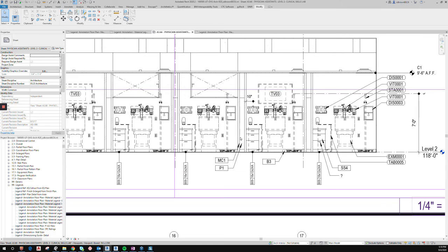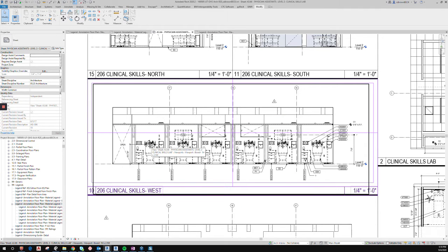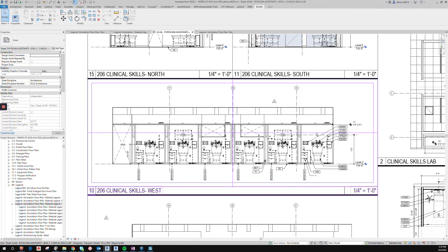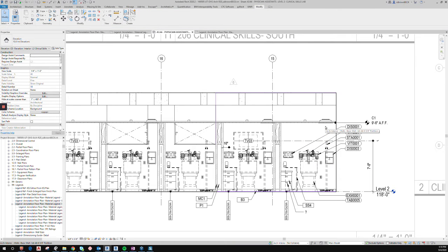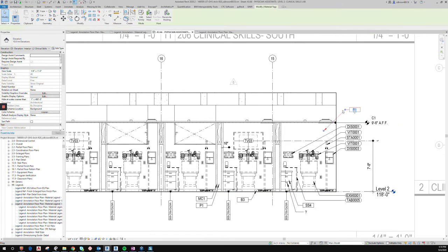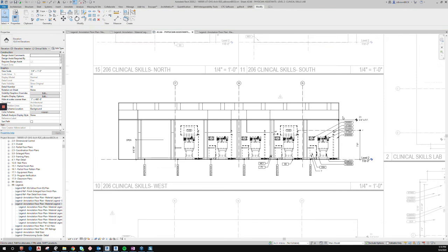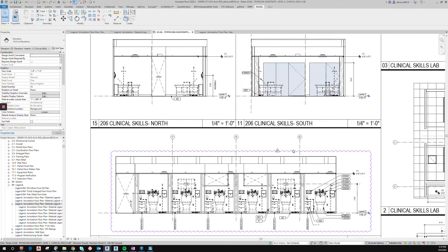And let's see, I don't think there's any special wall finishes. So there should be a note somewhere that all walls are paint P1 unless otherwise noted. So there's no need to put a whole bunch of P1 tags all over your plan. Only call out accent materials. So that's interior elevations tagging.